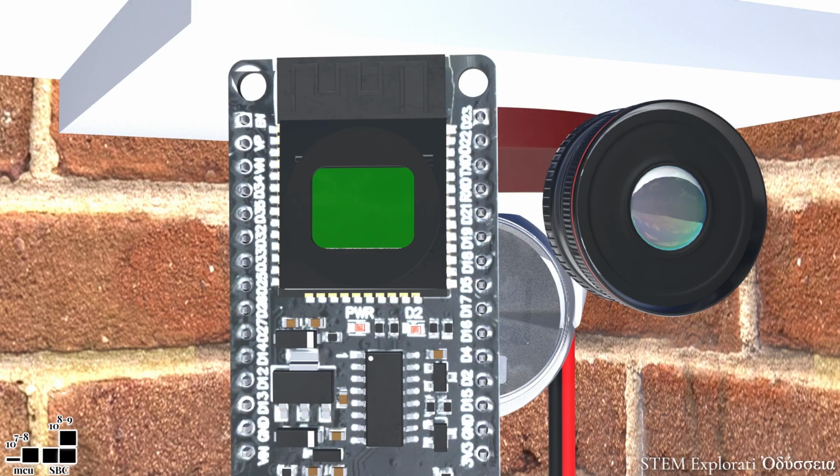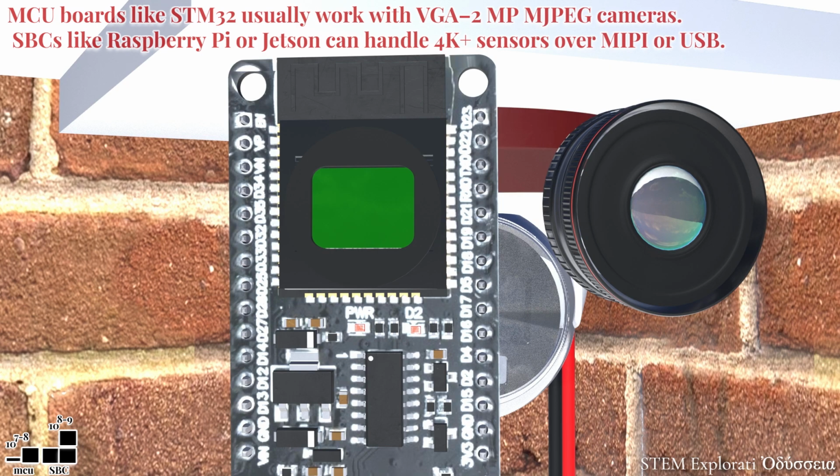Now, if you're working on a DIY project, there are camera add-on boards for microcontrollers, like the STM32 camera module. These modules handle the encoding and compression of the raw video stream, offloading the heavy number crunching from the MCU. The MCU is just there to manage the flow of data and provide control signals.